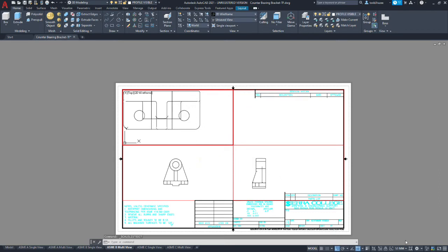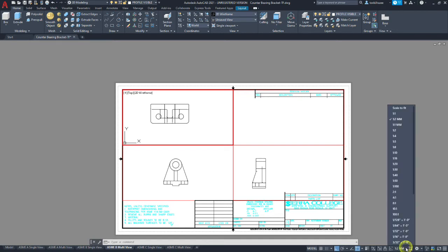And we'll do the same exercise of that same view. Now let's move to half scale in metric. That's better, but I still suspect we won't have enough room for dimensions. So the example was at an odd scale, which is 3:4. I'm not sure how that was derived at. I think the scale that's appropriate for this drawing and this size and the number of dimensions, 1/3 scale would work well. So we're going to do this just one more time.